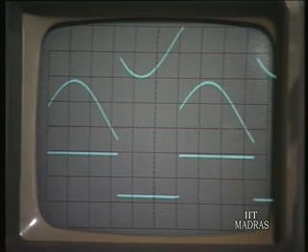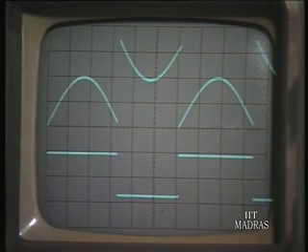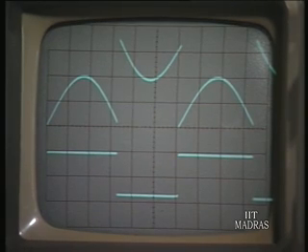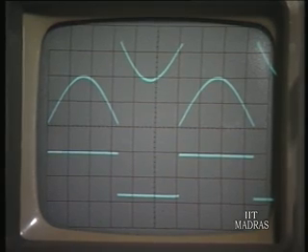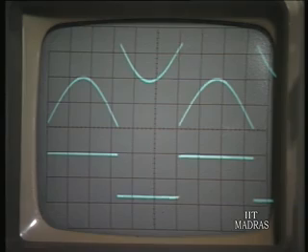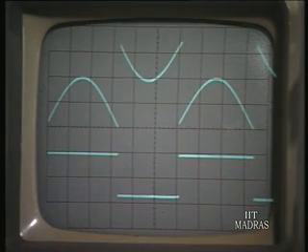Now please tune it so that it is exact. See, that is what is called tuning exactly, because now it clearly tells you how to do the tuning. Those two peaks should be symmetric with respect to the center point valley. That is the board waveform, and you can see exactly the same waveform being shown there.